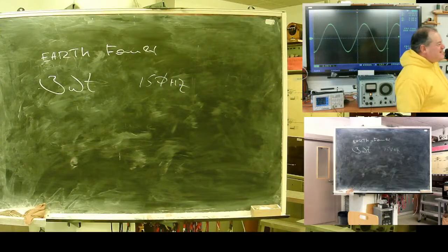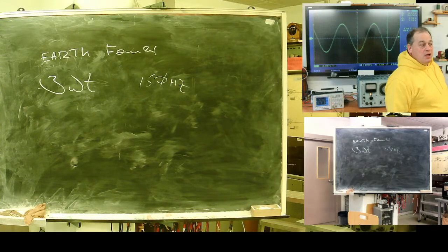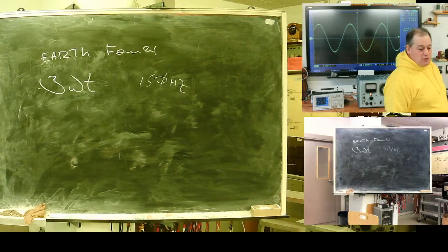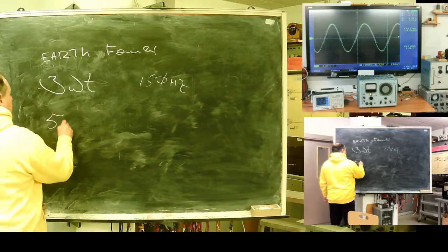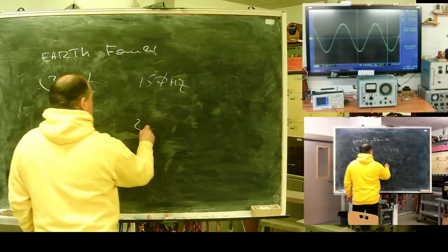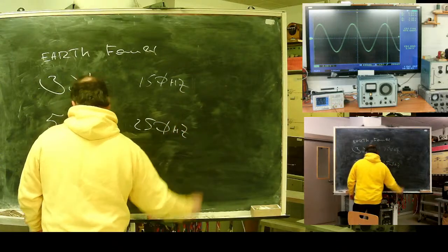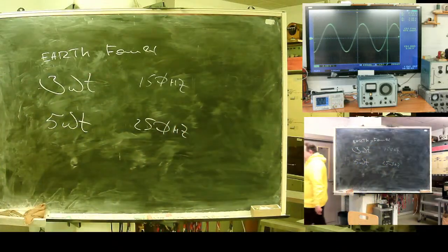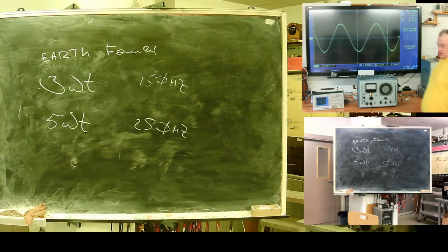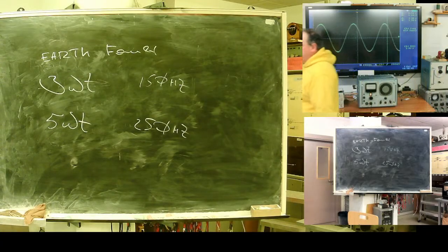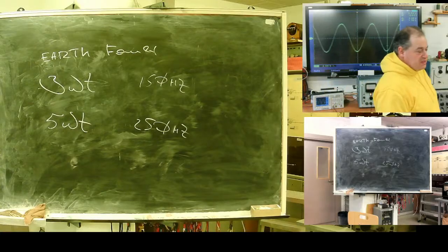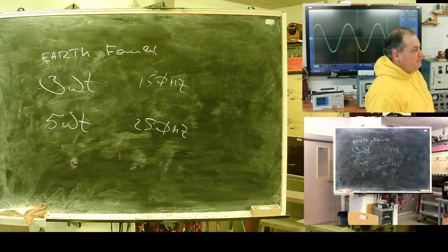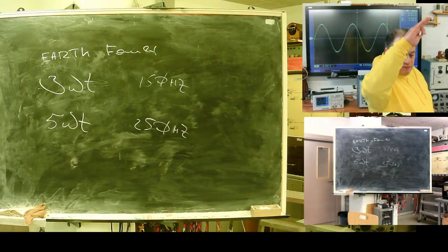One more moment. Protection devices that sense current transformer saturation usually need the fifth harmonic, 250 Hertz. So the typical usable signal range is somewhere up to 300, 350. Sometimes the 7th harmonic is also used. Cut off.